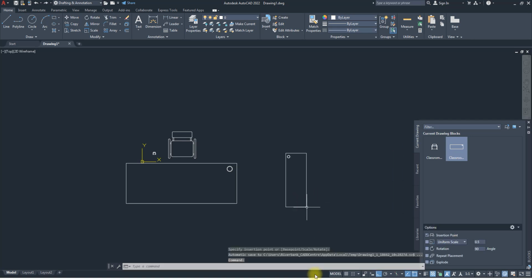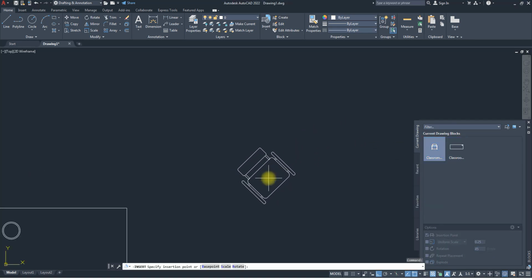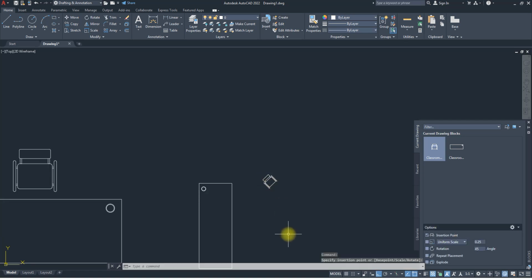All right, the interface is quite different. So any object you click will take this setting. So if the next one I want to bring in, I want to scale it to 0.25, I can just say 0.25, and then for the rotation, I want it to go at 45 degrees. Then any object I click now will take that setting. Do you understand?